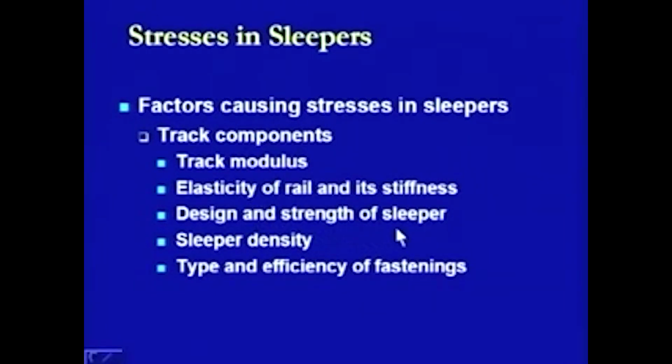Then the design and strength of the sleeper, this is another important aspect. Whether the sleeper is heavier in nature, what is the size of the sleeper, the loads which are coming at that sleeper, whether it is in a position to dissipate those loads or to distribute those loads to a wider area at the bottom, then that sleeper is fine. The sleeper density. Now, in the cases of the number of sleepers which have been provided, the sleeper density has its role. Though, as we have learned, the sleeper density has a smaller role in the case of the stresses being induced in rails.